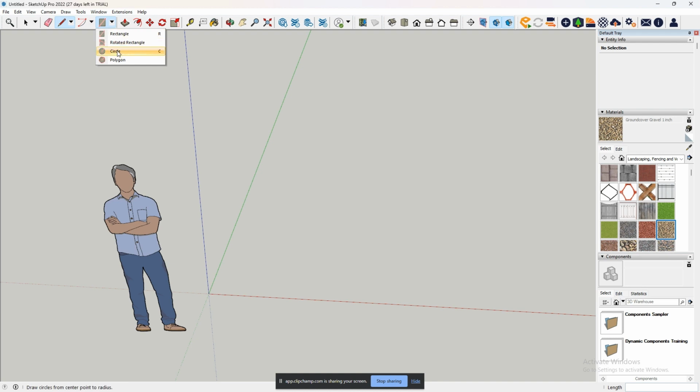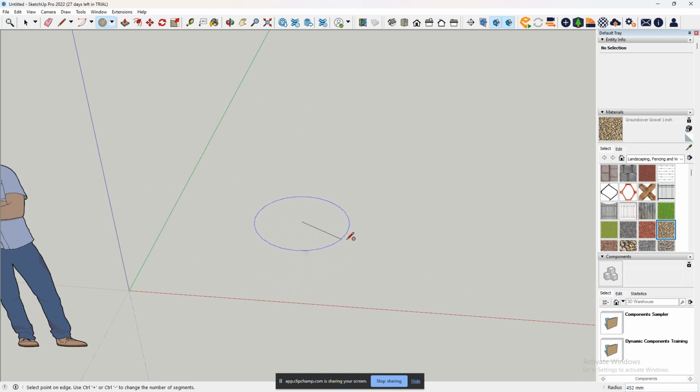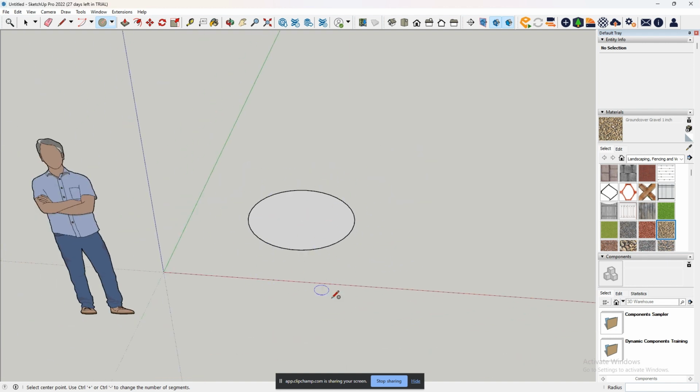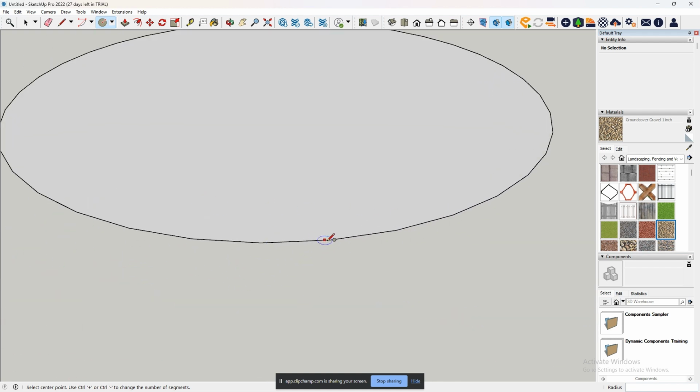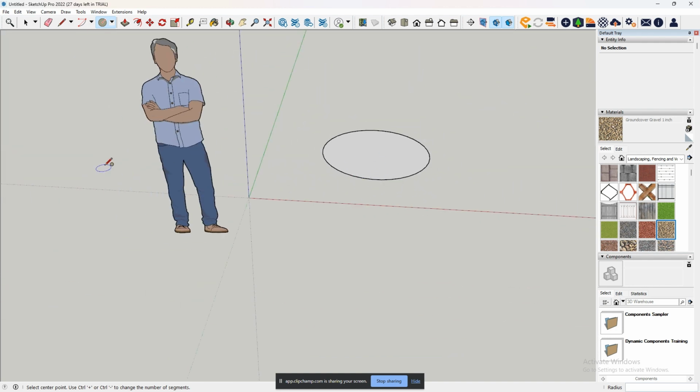And that typing in is also very useful for the circle tool, which normally you could just click once to get the epicenter of the circle, the very center, bring it out to whatever you want, and click again to release. And as you can see again, there's that jaggedness. So if you want to do it again, Control plus plus plus, much smoother. You can go on for quite a long time. You can make it even smoother and smoother. With the circle tool, you have to press Control plus quite a lot because it uses a lot more jagged surfaces, a lot more polygons, a lot more of these lines than an arc does, for example. But once again, you want to find that sweet spot between.